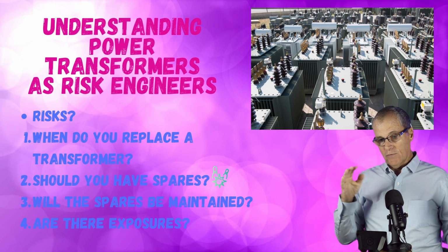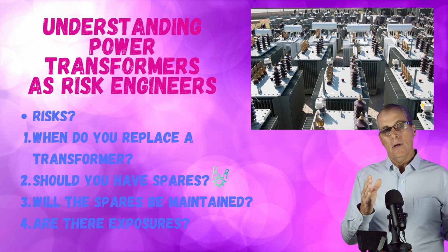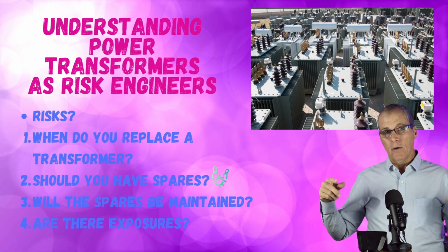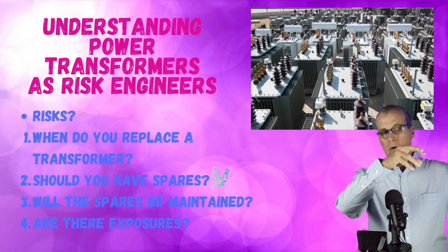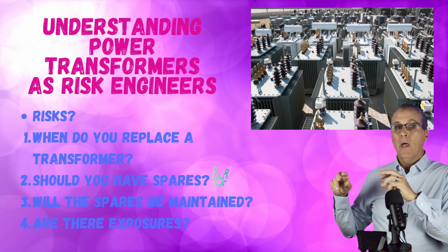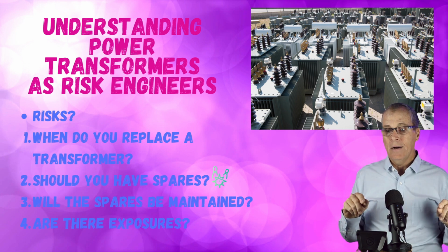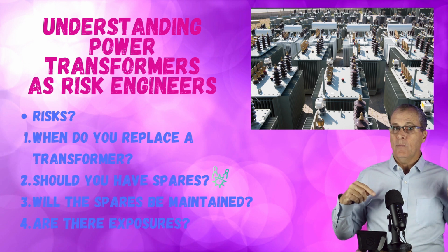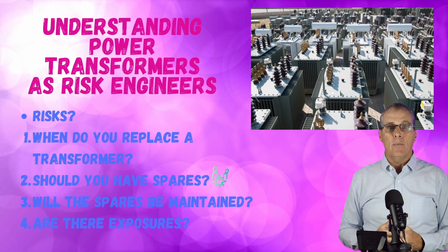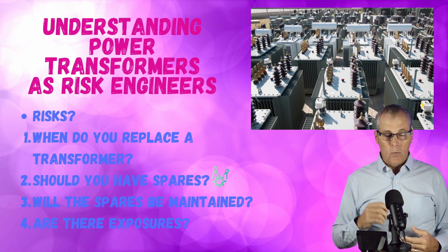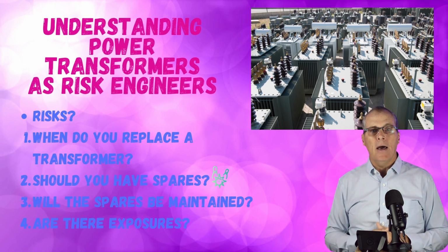So they had four transformers side by side over a common dike, and if any one of those failed and caught on fire, they had a manual deluge system that was basically valved with 2 valves. So you open up one valve and it puts water on these 2 transformers. You open up the other valve and it would put water on those 2 transformers. If either of the middle 2 transformers were on fire, you really needed to open both valves, but there wasn't enough water supply to do that. So in this case, we ended up replacing those 4 transformers with one new 3-phase transformer that was modern and outfitted with all the instrumentation.